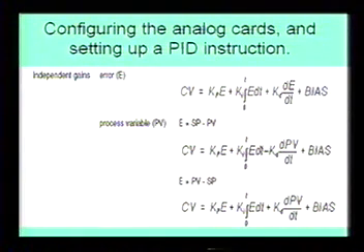Unless you get into some complicated loop that has a super long delay. We were trying to control an injection on a process, and you would inject this chemical, and then 20 minutes later you would see a change. That's a long delay. And usually the loop update times on these controllers are 10 seconds. So the Allen Bradley processor would say, okay, turn on, make a change, and then check 10 seconds later and say, hey, you didn't increase.